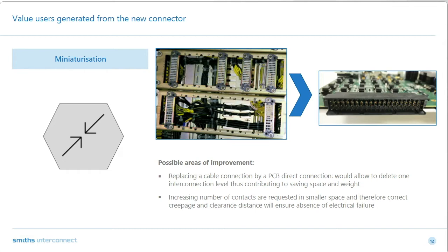Now, while designing the next generation that respects this overall architecture goal to reduce size and all the collateral benefits that we talked about, we have to be mindful of the creepage and clearance distances that I talked about. Because remember that just reducing size is not good enough.